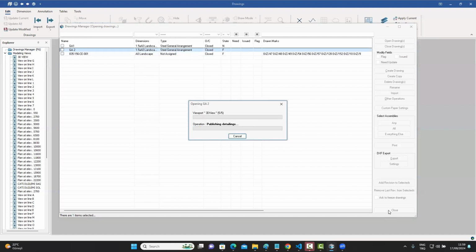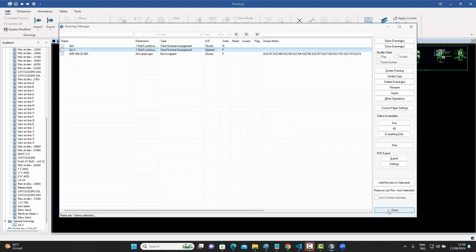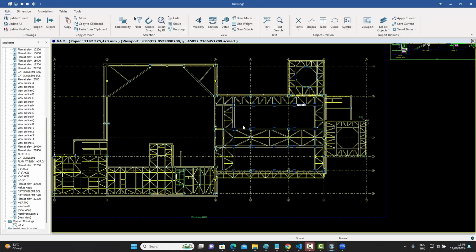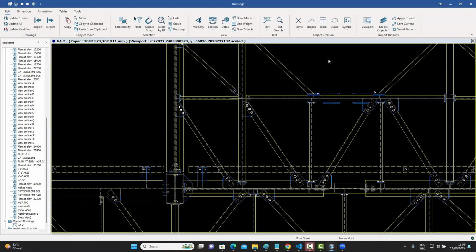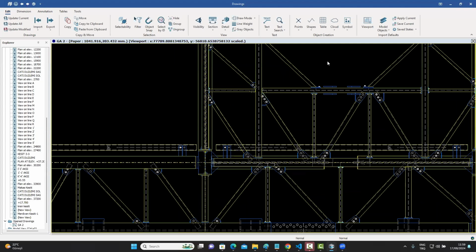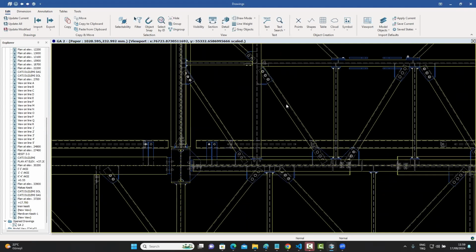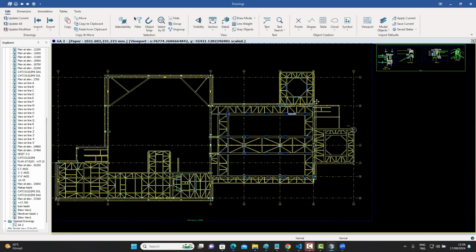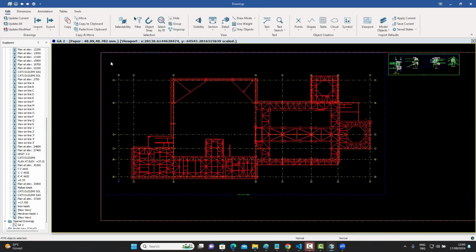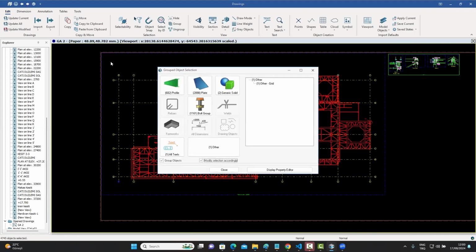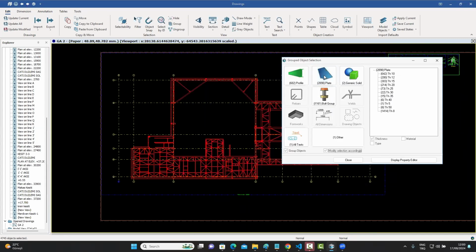And let's say the change I want to do is, so we've got beams and horizontal braces and columns over here, as you can see on the screen. But I want to basically change the color of only the horizontal braces on this floor. If I just select, normally it would be quite a headache, but if I just select the entire floor over there, press enter, and if I go to the profiles over here, and I say I want to group not the section name, but the beam group.